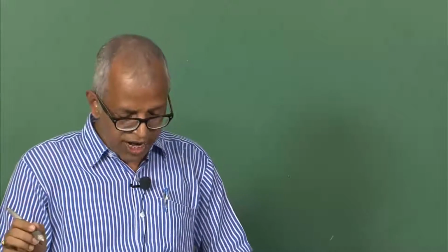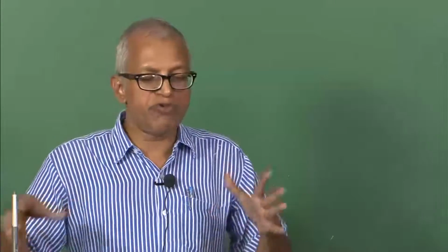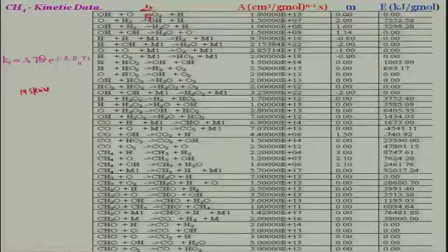So now, as I told, people are using very long numbers of reactions in chemical reaction mechanisms for methane-air and other higher hydrocarbons, because nowadays CNG is being used, which contains methane but also some other higher hydrocarbons. But higher hydrocarbons mean more species involved, more reactions, and it will take a lot of time to compute, right? Unless you have parallel computing, and if you are doing a very complicated problem like an internal combustion engine, gas turbine engine or rocket engine, it will be a hell of an affair to predict something meaningful using kinetics.